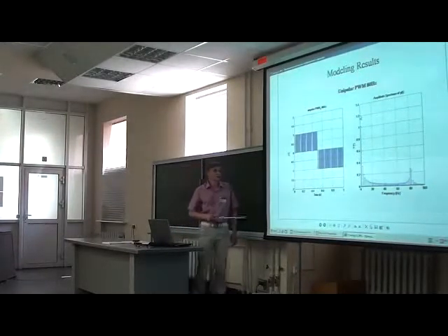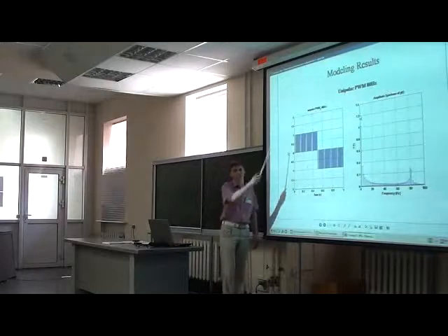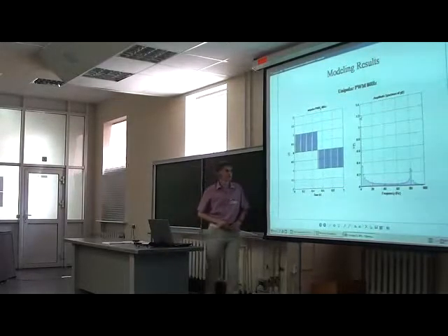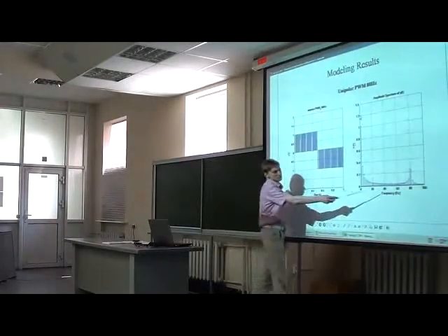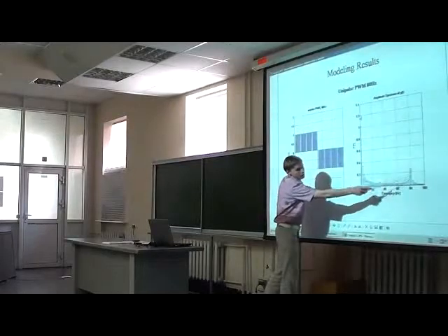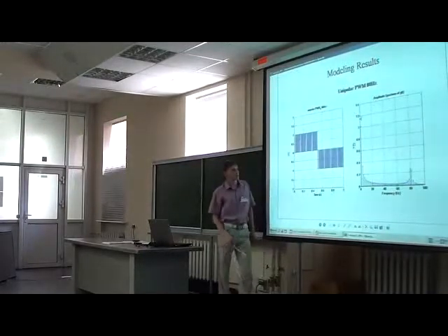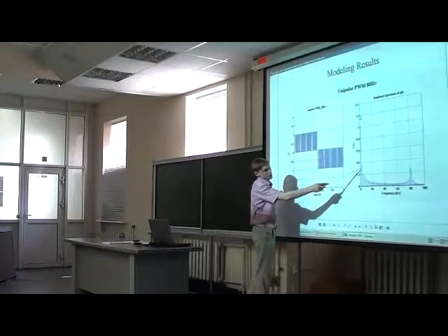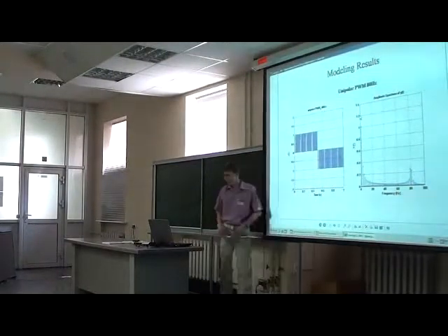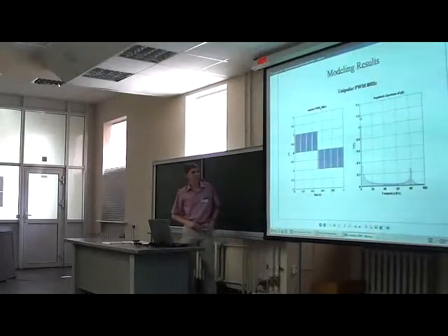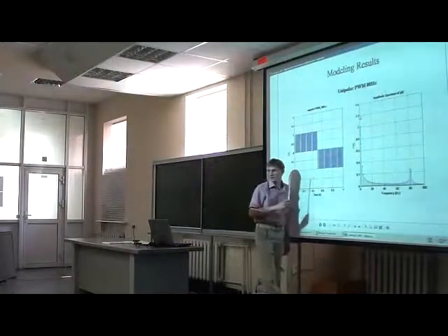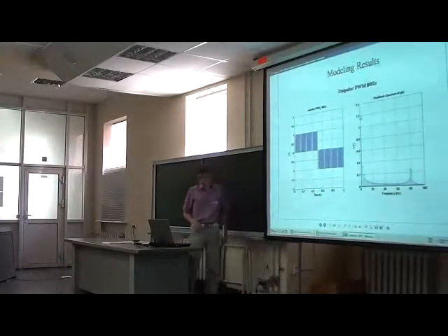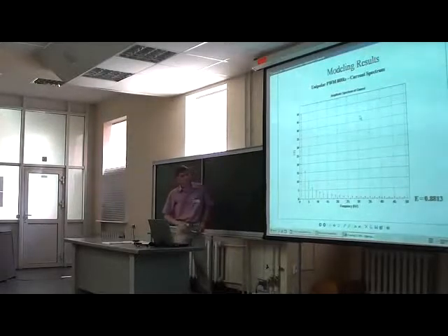When we generate PWM pulses on frequency 80 Hz, we get this figure. And we can see that we have this 80 Hz harmonic. But here also the third and fifth harmonics are very big. By increasing the PWM frequency, these peaks moved to the right. Here is the electrical efficiency of this signal.